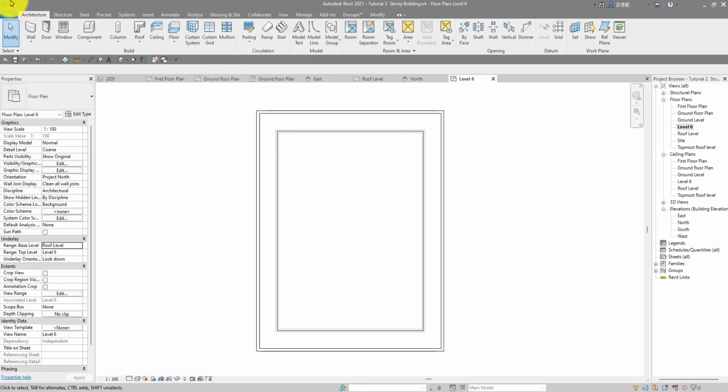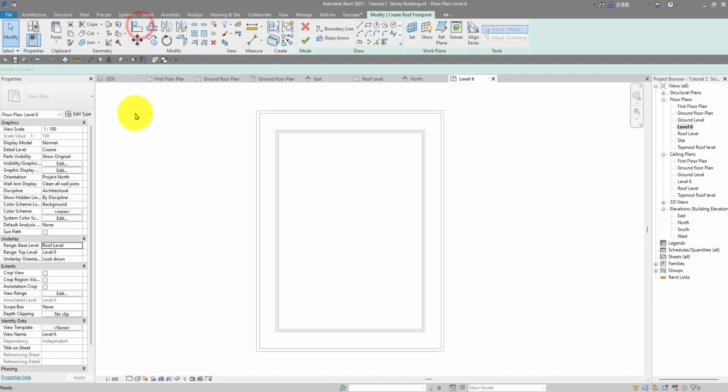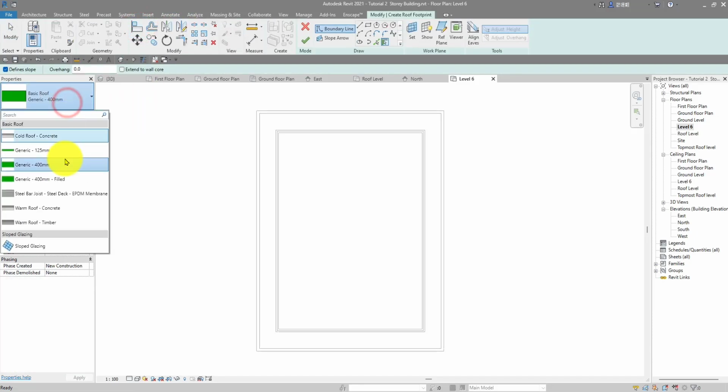So all you have to do is go into the architecture tab, and then you move all the way to roof. When you move to roof, you're going to have this. Revit has some roof installed. We have a wall roof. Revit always has some families installed in every section, alright? It has some installed by default, but some you wouldn't get in. Some of these items I wouldn't get in maybe a later version, or maybe in the current version, alright?